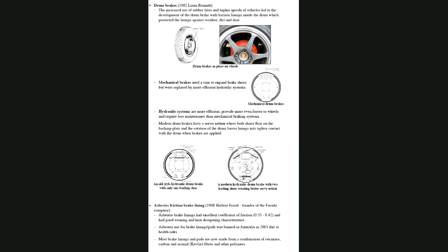So what they've got down here is that you've got floating brake shoes, and they're just connected roughly there, and you can move these up and down so that when you put your foot on the brake, this lining goes out, and if the brake is going in this direction, it tends to drag the lining around.